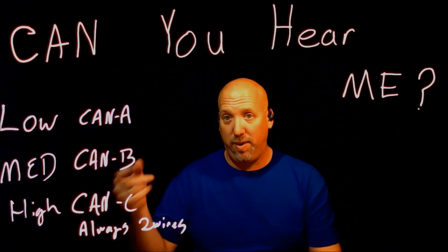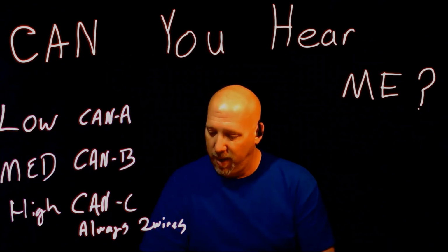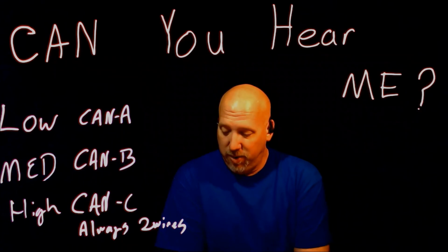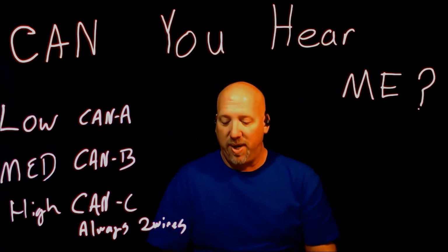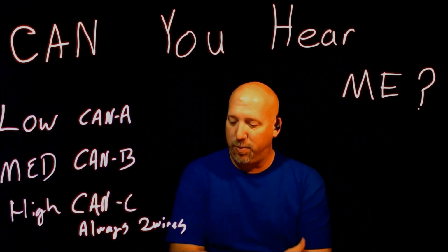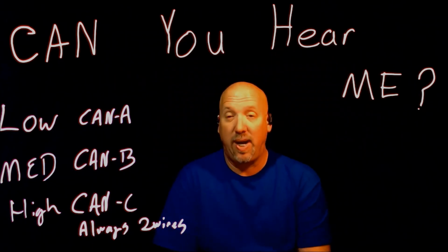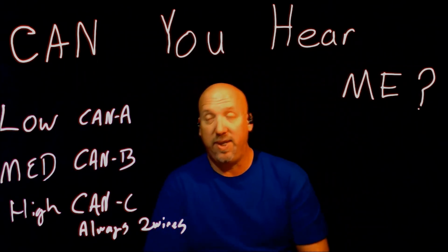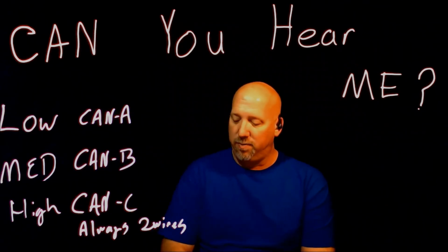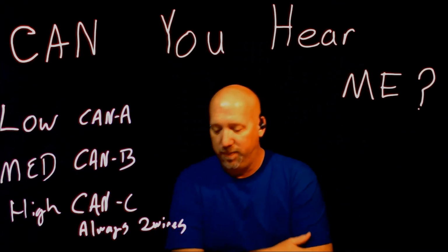That's the wire we talk about. 120 ohm resistors, 60 ohms total resistance there. CAN C carries generic OBD2 data to all modules on 2008 and newer vehicles for inter-module communications, but did not provide DLC communication before 2008. Even when CAN C was ported to the DLC, it was not always raw data. For example, Chrysler has a separate diagnostic CAN C circuit from the Central Gateway, the CGW. The data from the CGW is always CAN C, but it's only requested by the scan tool.